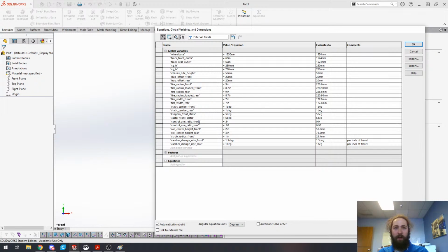And then you start to figure out a few things about, well, okay, what's the ratio my control arm is going to be, of the length of them, and then also where's my roll center going to be, and a lot of stuff, as you'll see as we start diving into this, is dependent on outboard packaging.